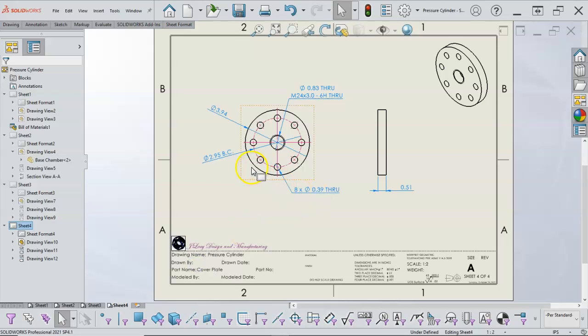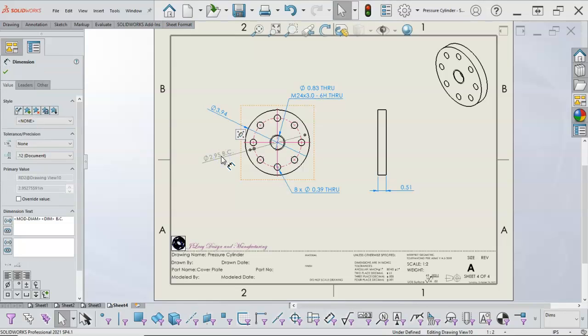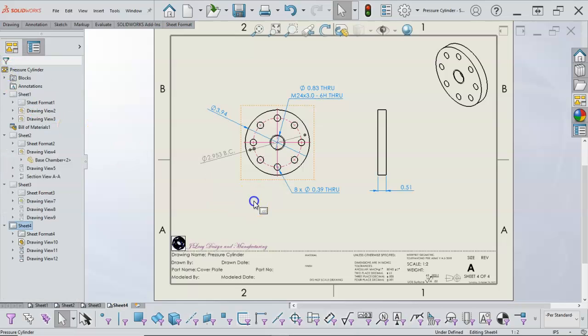And then when we go to the outside, the bolt circle, that would be our critical in 3 decimal places. And then if we were to make another pass, 4th pass, it would be to look at the positional and do we need flatness and parallelism. The standard surface finish should take care of anything that the neoprene can compensate for. And so overall, that gives us a drawing package.